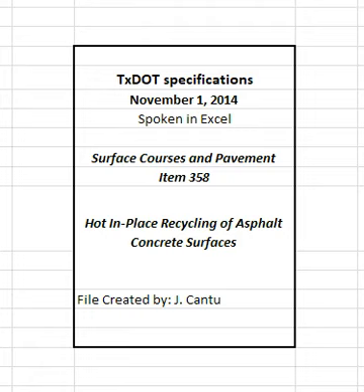After the project is awarded, obtain an adequate amount of roadway cores throughout the project to perform the mixture design and to determine the existing condition of the roadway to account for any variability within the project limits. Evaluate the material from the roadway cores and document any existing material that could be detrimental to the process: rubber seal, fabric underseal, etc. A minimum of 2 inches of the existing pavement structure must remain in place following milling. Document any base or uncoated material within the layer to be recycled. Provide documentation of any of these conditions before proceeding with the mixture design.